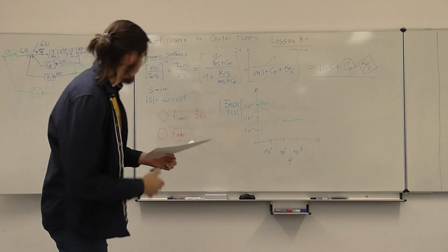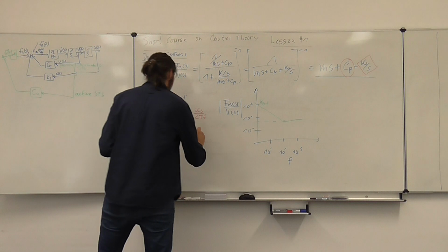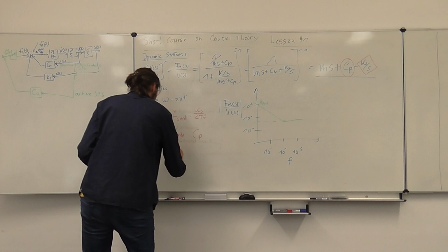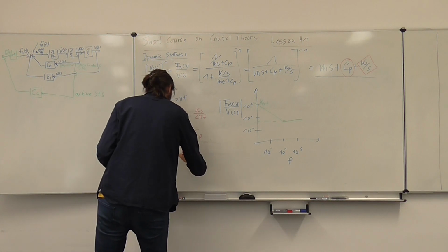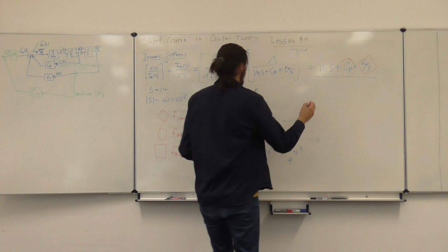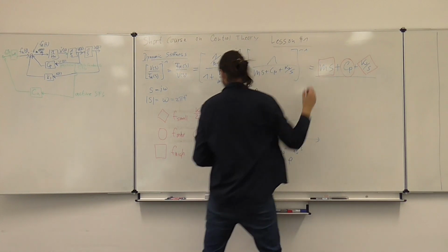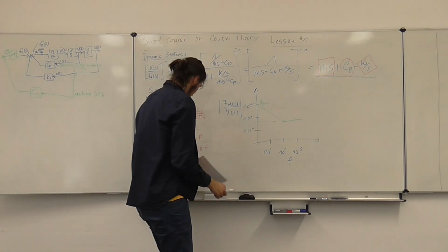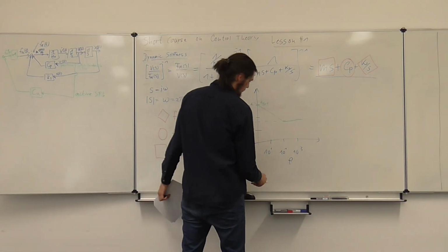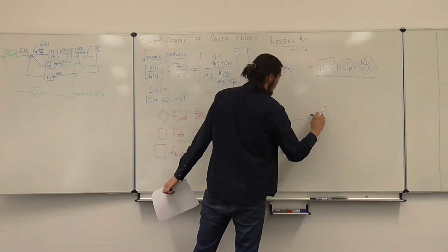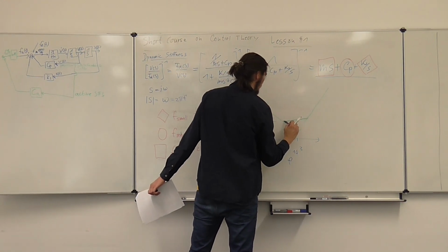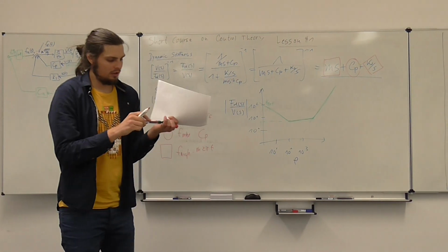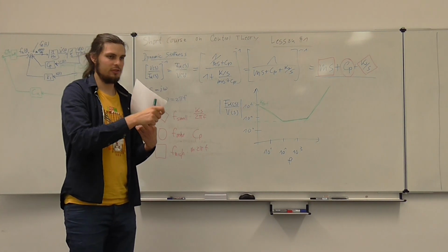And at very high frequencies, obviously something else will dominate, and that is our m times s, so m times 2 pi f. Because that's always going up, starting at 0 and going up here somewhere, and then it will start to dominate. So that's basically naturally how this system would look from the disturbance.